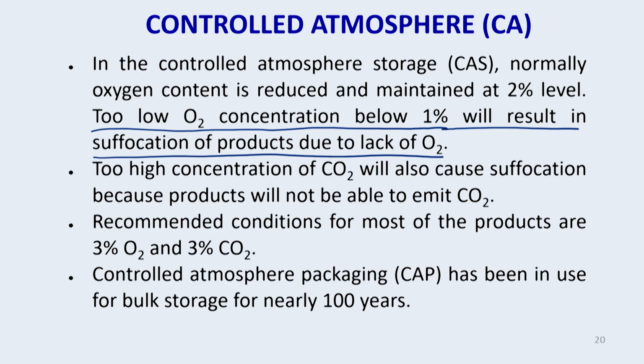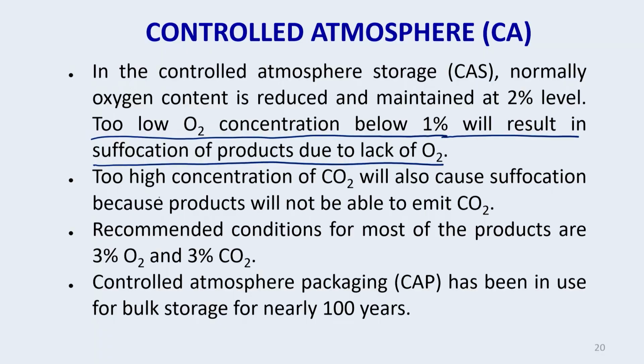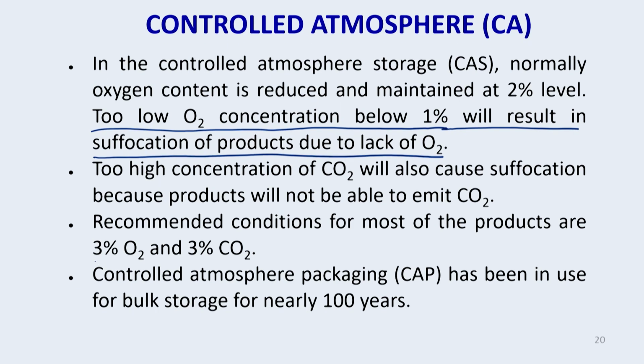If you have carbon dioxide, there are chances of preventing microbial growth, whereas if you have more oxygen, there are chances of promoting bacterial growth. Too high a concentration of carbon dioxide will also cause suffocation because products will not be able to emit CO2. Recommended conditions for most products are 3% oxygen and 3% carbon dioxide.